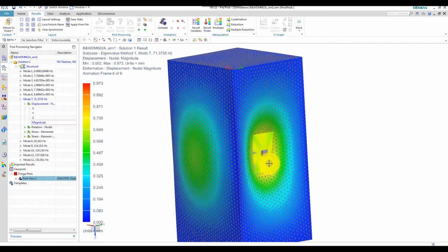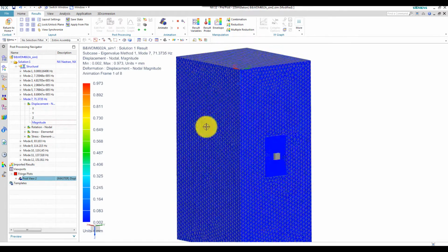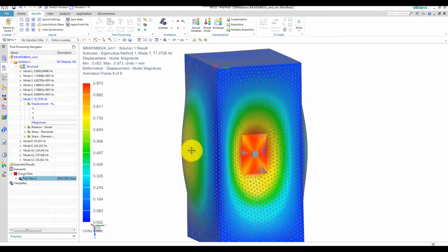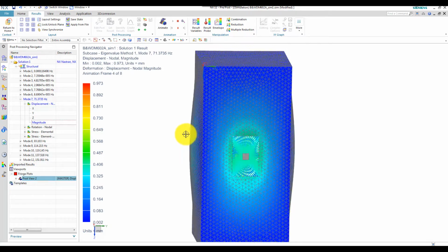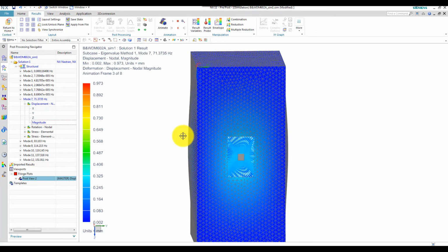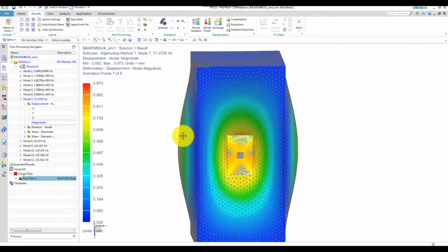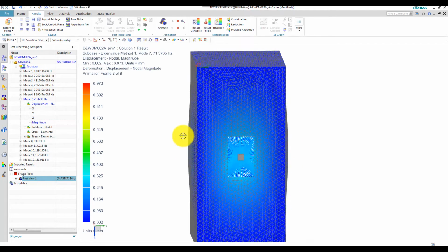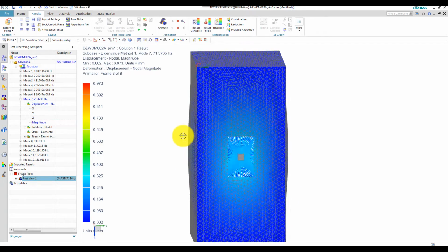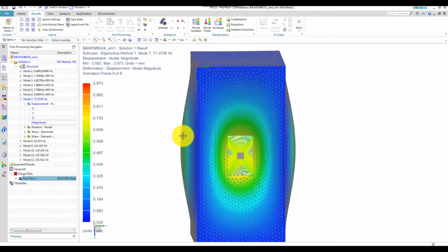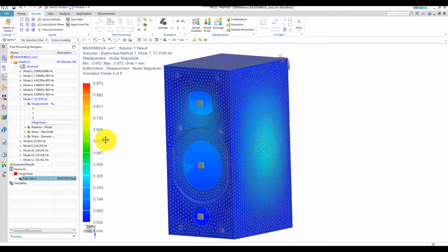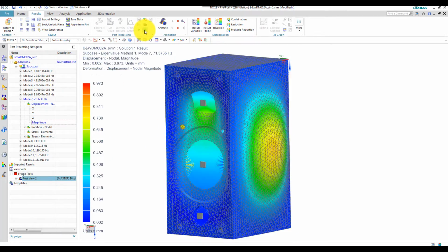And if we want to increase this eigenfrequency, we can reinforce the loudspeaker where you have the largest displacements here. And remember, this is just a scaled eigenvector. It's normalized, so this doesn't say anything about if this mode shape is actually being excited. It might not, but since the E string is quite close to this eigenfrequency, we should do something to avoid that risk. Let's check out the next mode.